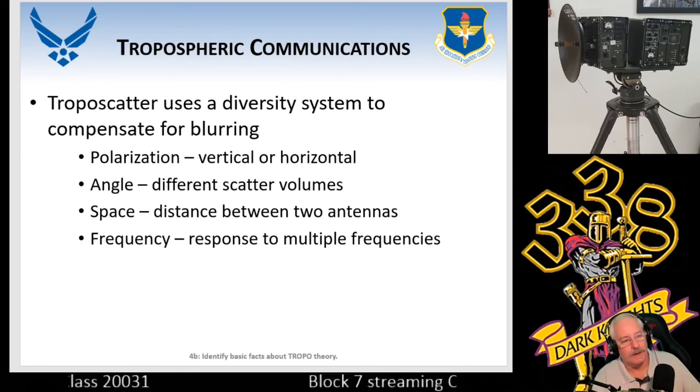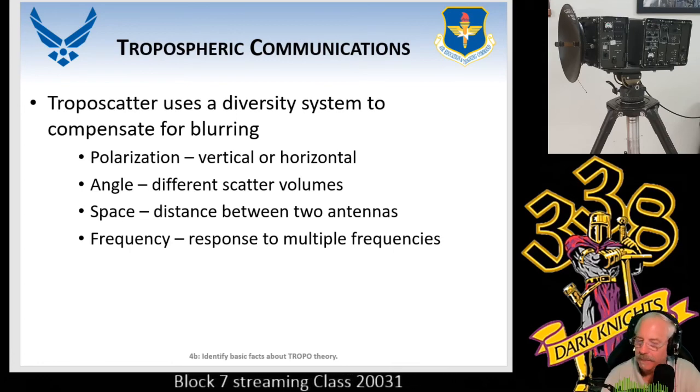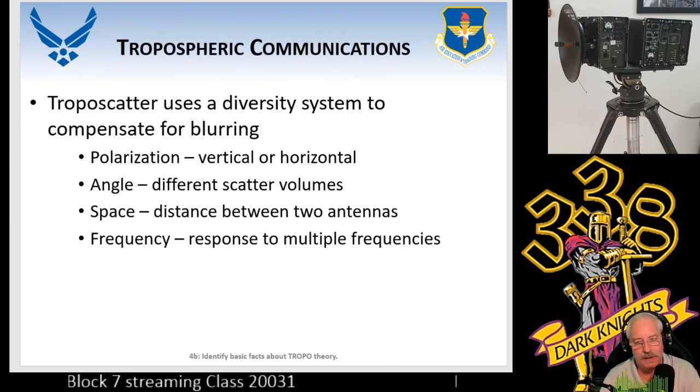The idea here is the way this is going to work, the frequency, you're going to have two different frequencies. You're going to have a separate transmit, you're going to have a separate receive, and those two will be no less than 200 megahertz apart. They have to be more. They have to be in that 300 to 400 megahertz apart to really get good. But you can get them 200 megahertz apart.